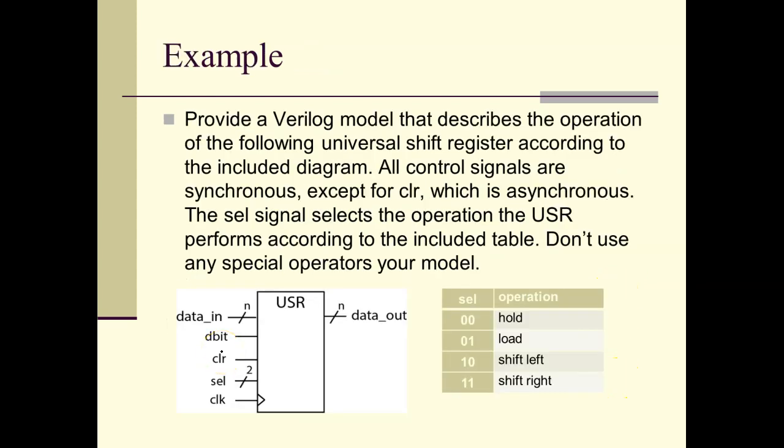Some shift registers are just not configurable, but heck, you can design it any way you want. We're going to go through an example here, and this is a universal shift register. What I need to do is just declare what's synchronous and what's not. The thing that's asynchronous is the clear input, which we've seen before. And these are the operations that I'm going to do on it: hold, load, shift left and shift right. These are just simple shifts, so shifts of 1 bit position.